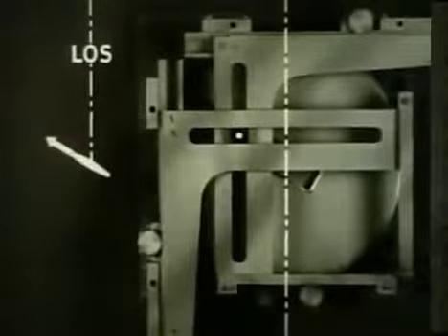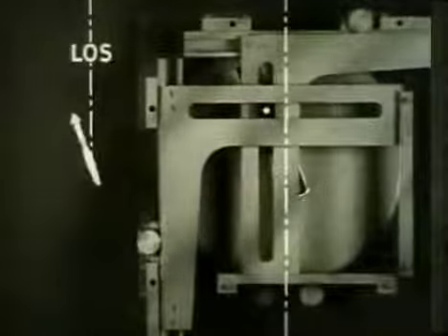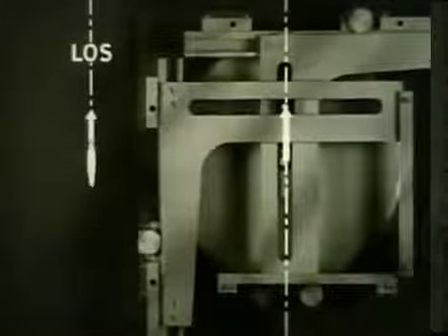When own-ship's course is along the line of sight, the bearing rate component becomes 0, and the range rate component is equal to the speed vector. At 0 speed, both racks cross at the center, and the outputs are 0.